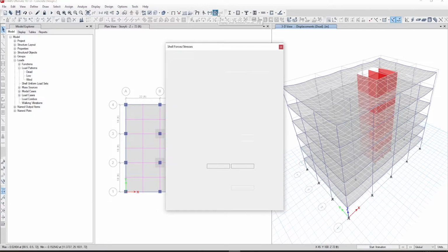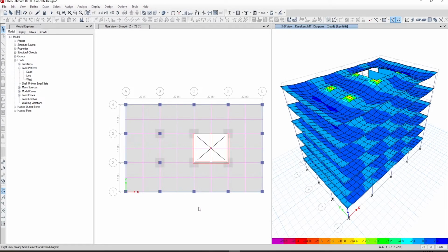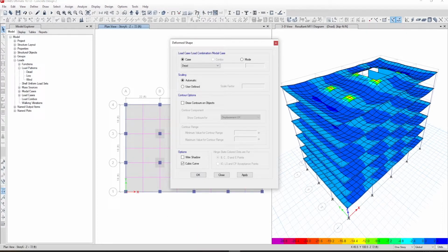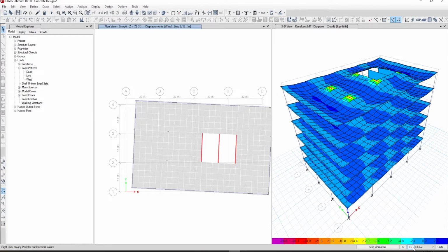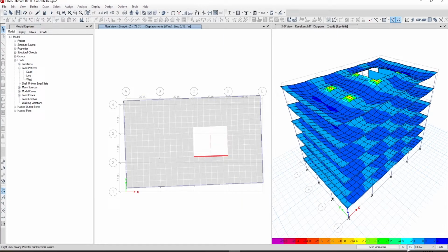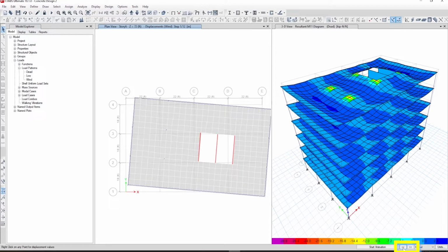You can use this form to display the wind load deformation of the building model. Each of the deformed shapes due to the 12 different wind load permutations, as specified by the ASCE 7-10 code, may be viewed by clicking on the VCR buttons.